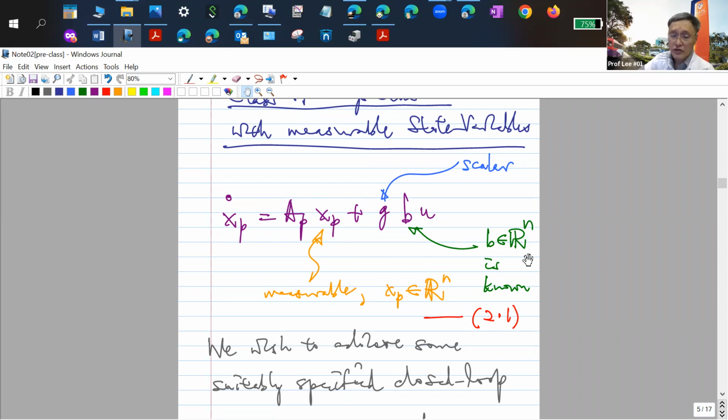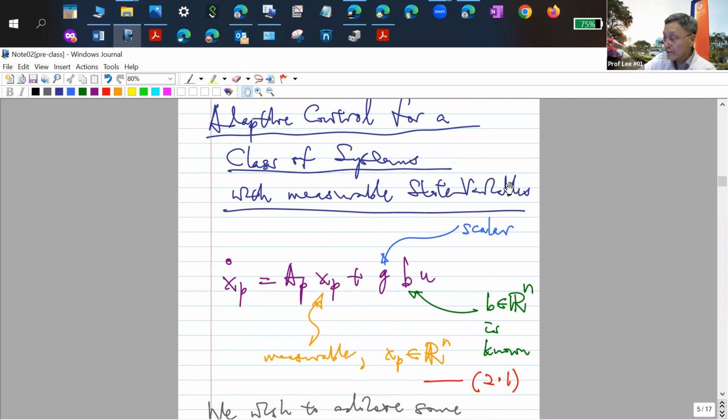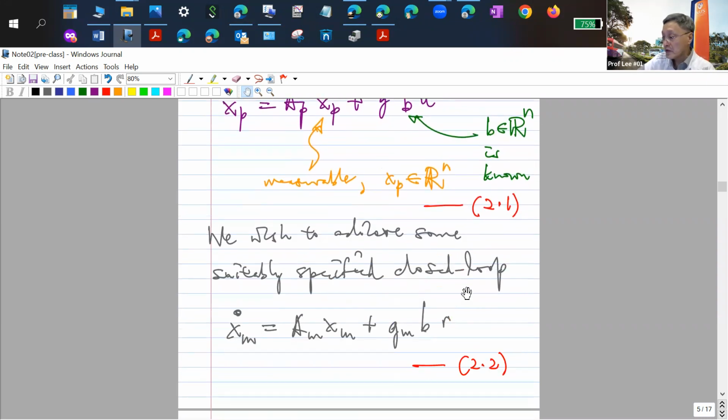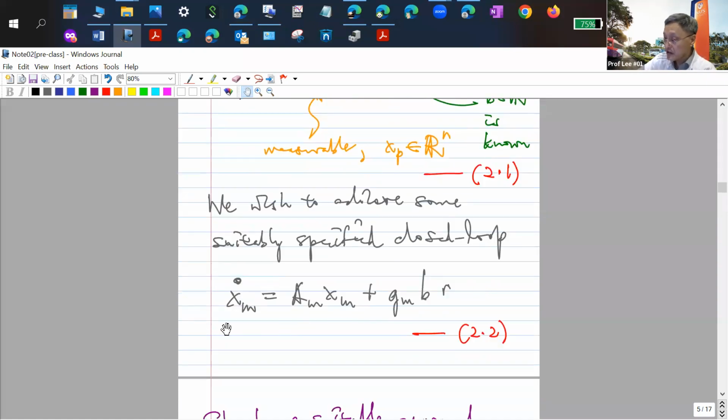How will I do control? If you have taken 5101, or my several students down here who took 4302 with me last semester, you give me a system like this. I'm not talking about adaptive control. How will I do just control, full state feedback control, because all the state variables are measurable? Again, this is the kind of performance I want, specified through a reference model.